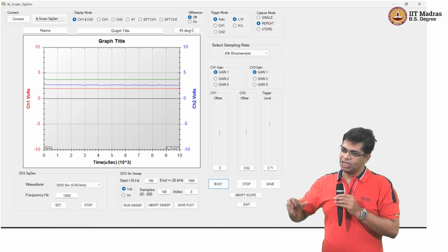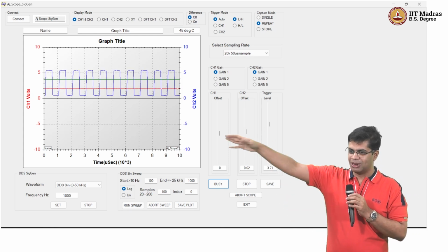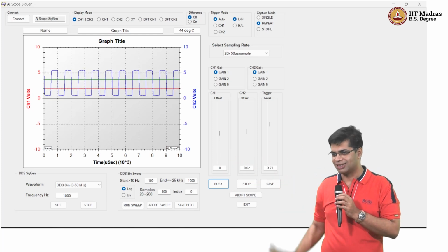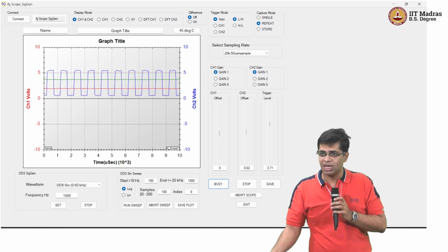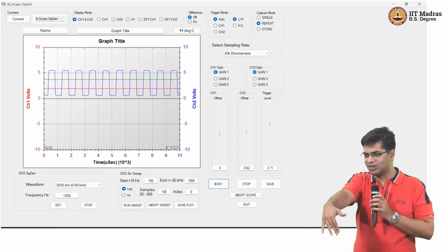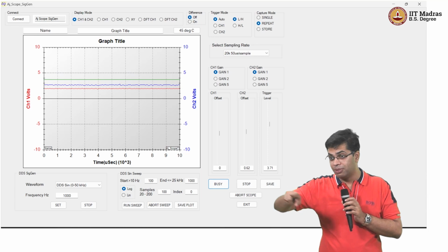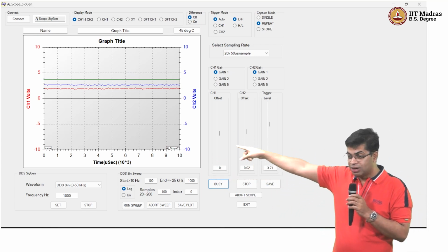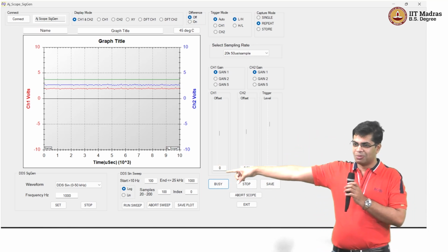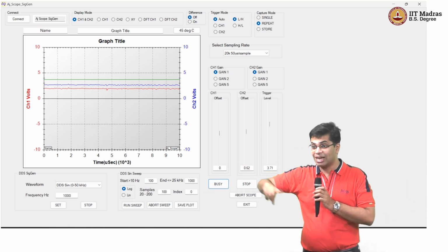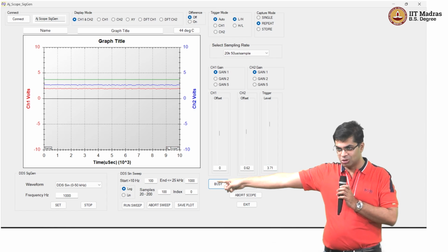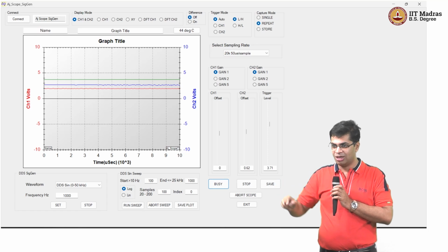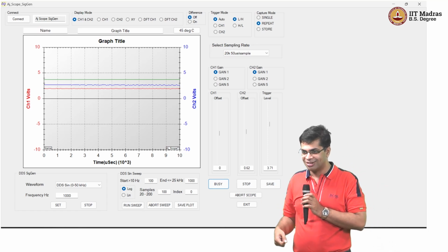If I do digital gain multiplication on that poor A to D, I'm still going to get all the artifacts of the poor A to D in my result. So you would want to improve the input stage gain first, then take it through. Remember that the way we have set up has a mandatory reduction by a factor of 10, and only then we're doing A to D. So already we are struggling with a reduction of 1 by 10, and over and above that, you have a weak signal.